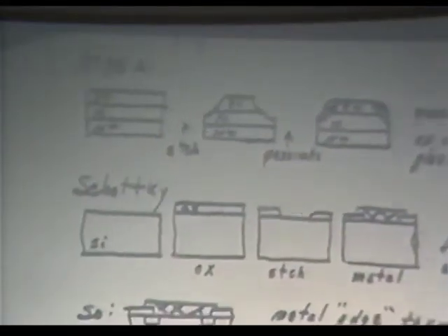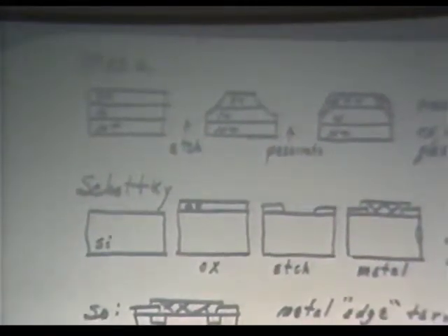Double diffused. All we've done is to put in a layer from the other side, and incidentally I flipped that on you in the picture, but at any rate, to try to cut down the series resistance we get. Instead of starting with epi, I kind of did it as an afterthought with another diffusion. Mesa devices are still used many times for high voltage.